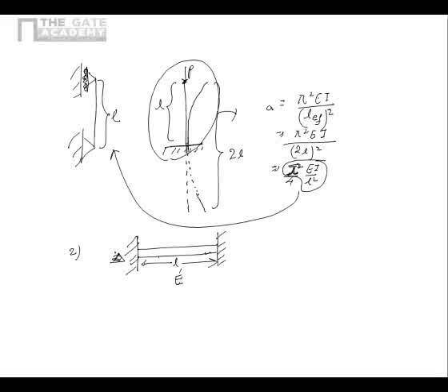Now obviously I know that because these two ends are fixed, the length increase is not possible. Now I pose the question, what is the delta T required such that if that increase in temperature is applied, the bar will buckle, assuming that P critical is the critical load for this bar.